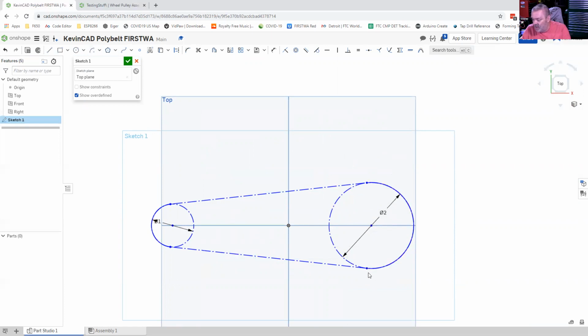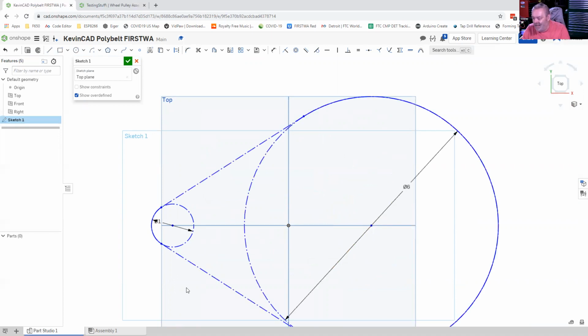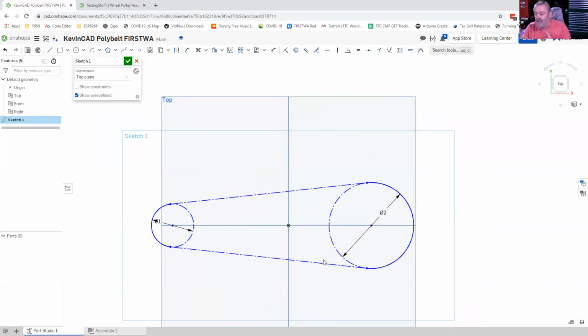You can see that solid line, and I'm going to do something extreme. I'm going to give this a 6-inch circle. And you can see that the end of our construction line is following that tangent point, and that tangent point is connected to that arc. And that's really important because for this to work, you need that malleability and for it to follow that geometry. Okay, that looks pretty cool.